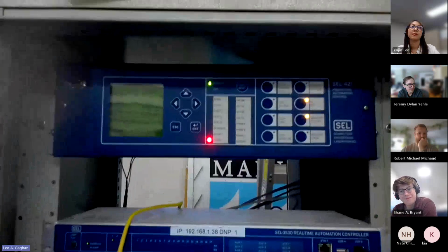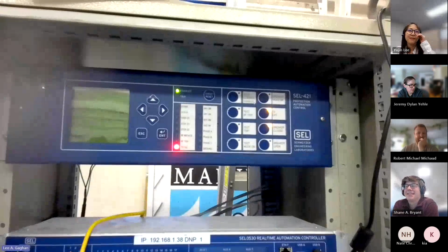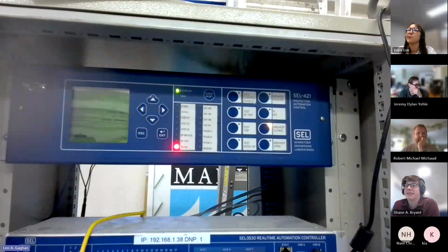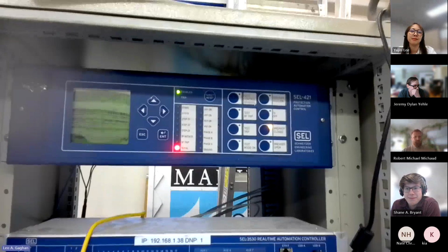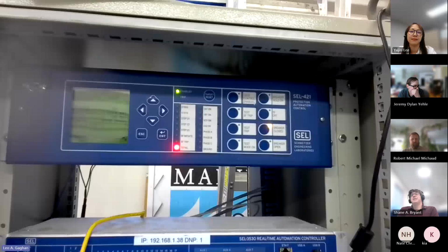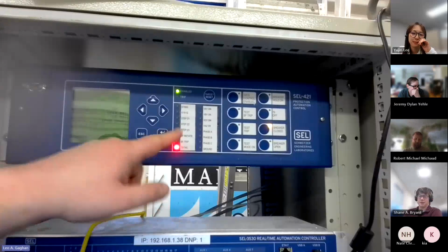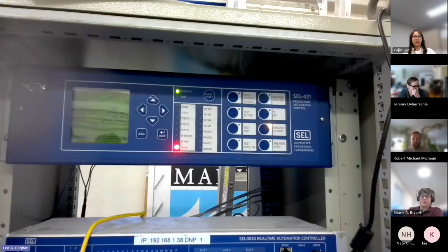Oh, yep, because I turned it off. So I've got to turn the function on and turn the LED off. Unfortunately, when you turn that off, it drives reclosing to lockout. We've got to wait a second for that LED to drop out because it won't let us do reclosing. That does not drop out, but I'll explain what we're trying to do here.